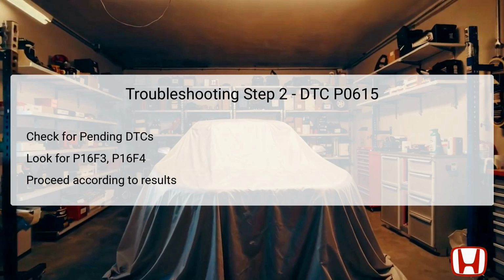The second troubleshooting step involves checking for any pending or confirmed DTCs once again using HDS. This check is critical as it helps determine if related issues are present.